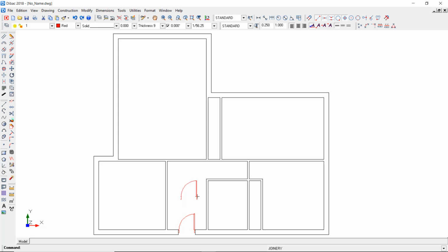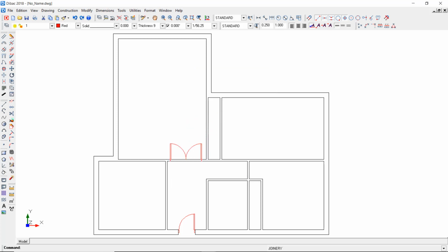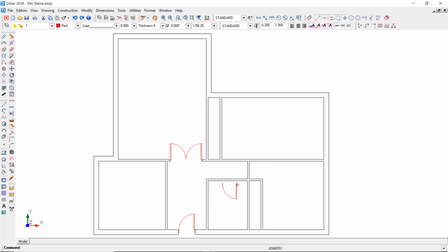If I want to change the door settings, I can double click with the mouse and set the new door parameters. Now I can place this double door in this wall, for example. I double right click again to change the settings of a new type of door. In this case, the length of the door will be 0.725. Now I place these doors in their respective partitions.